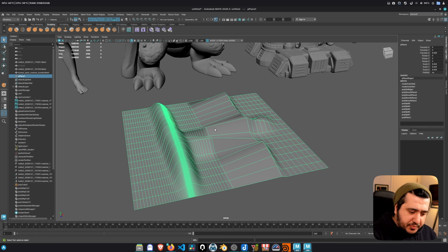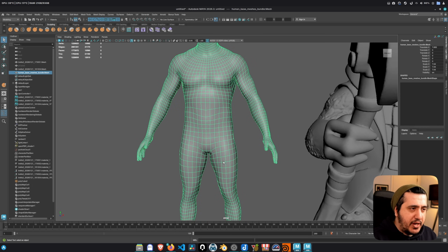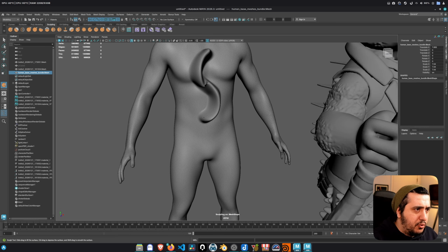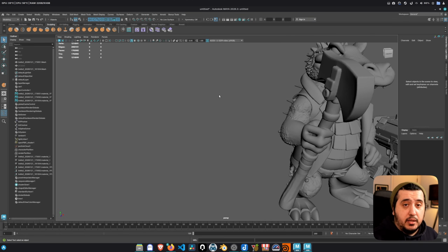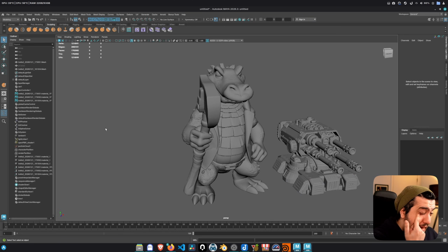That's why clean, evenly spaced quads matter. When we talk about the topology not being good, or when we hear that something has a bad topology, an example can be something like this. When you have proper topology like this, when you sculpt this and subdivide, you are going to get so much finer results. That's why, as of now, I am telling you again, retopology matters.